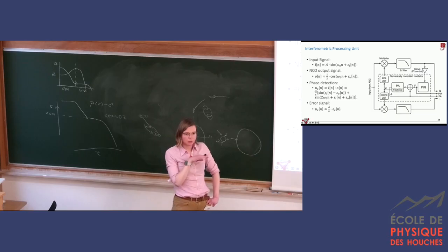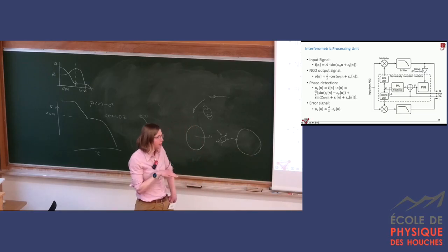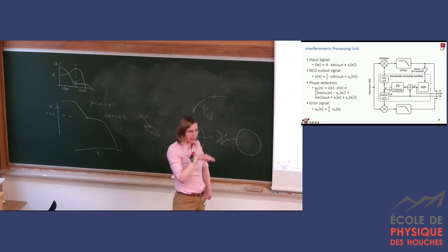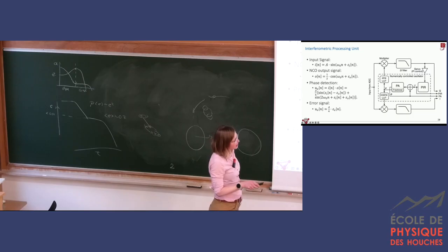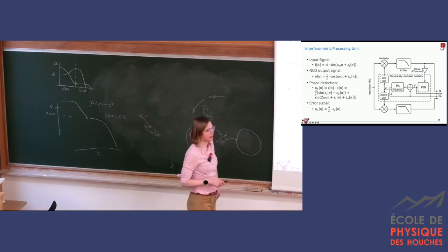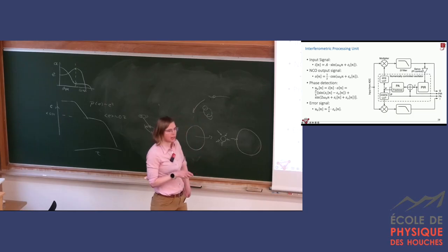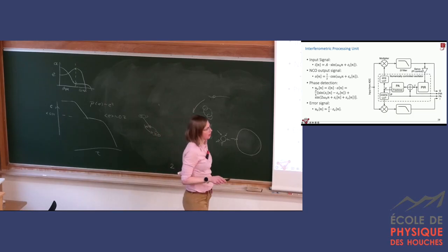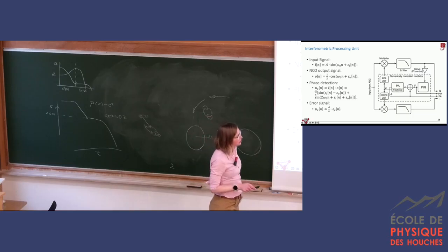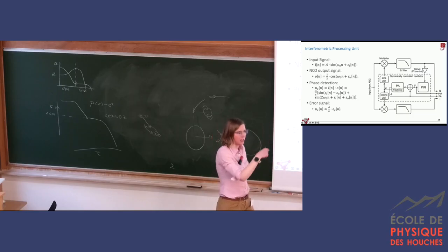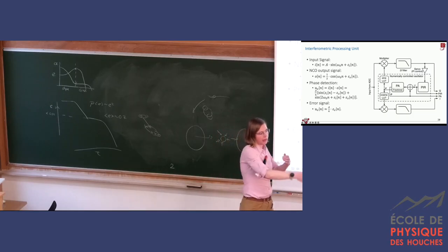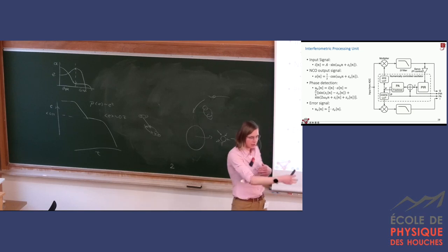The only thing it wants to do is make sure that our Q value is close or at 0 exactly. So the output of this controller is going to be a copy of our argument, right? And this is being used to feed back to our sine and cosine copies and close the loop. So this is running in a loop: instantaneously you receive the signal, create a copy, send further, create the copy, send further.